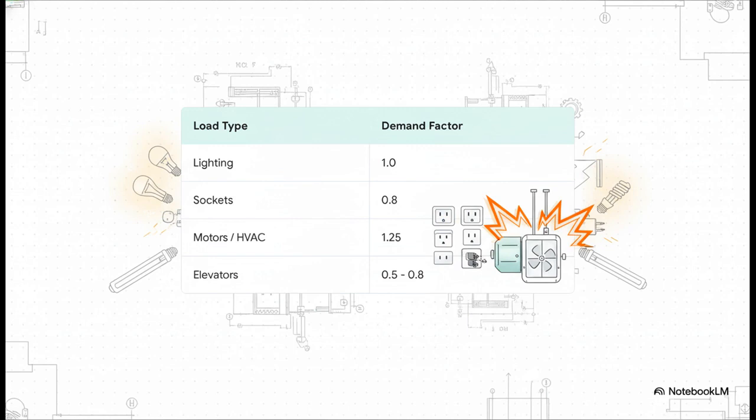So why the extra juice? Well, think about that initial kick they need to get going, that in-rush current. We have to account for that. This isn't just guesswork, it's smart engineering.